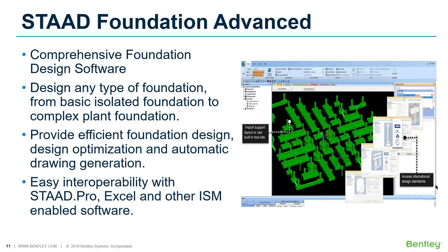So if you model your superstructure in STAAD.Pro, you can easily transfer your support reactions into STAAD Foundation for the foundation design, or with any ISM enabled software. Also, you can export your data from Excel to STAAD Foundation directly. And once you have performed the design, it will provide you a detailing drawing, a design optimization, and also a calculation sheet with all the reinforcement details.